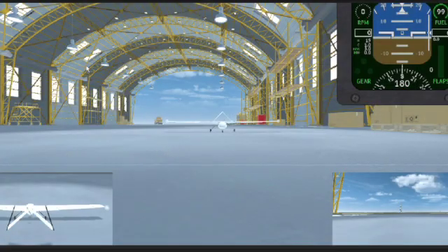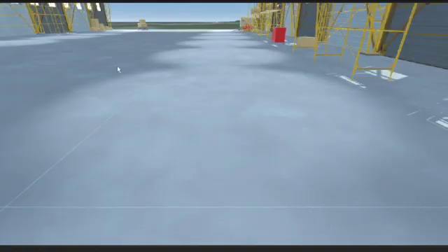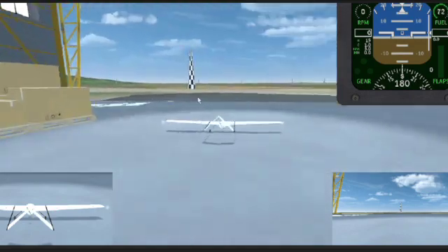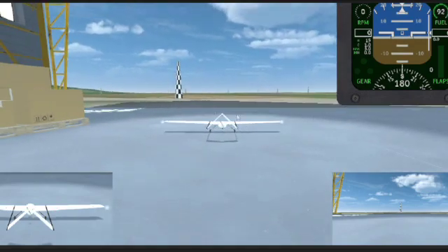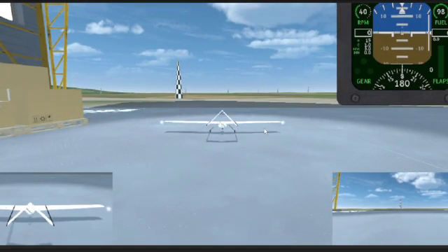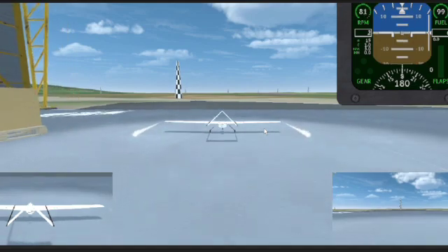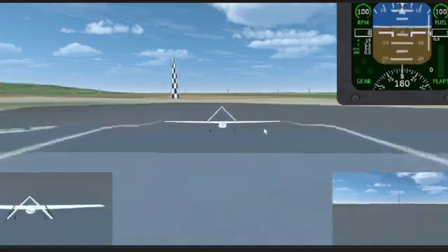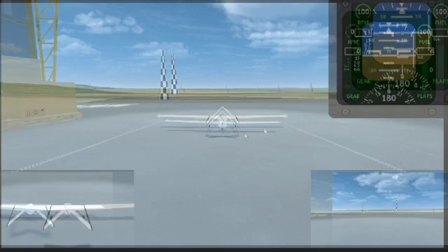This video shows the UAV responding well to control inputs when maneuvering on the ground, which implies that the center of gravity position at 0.05 is acceptable. The UAV should also maintain speeds below 5 meters per second when taxiing, as above this could lead to the UAV drifting.